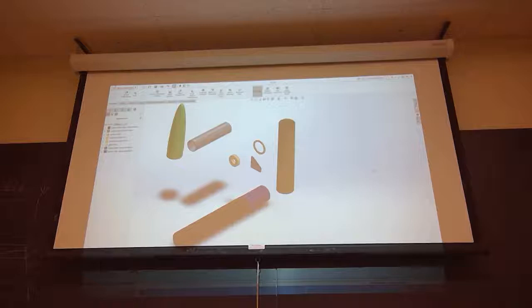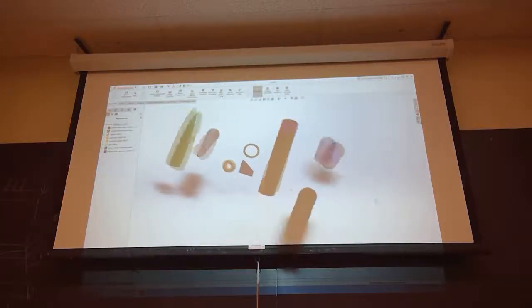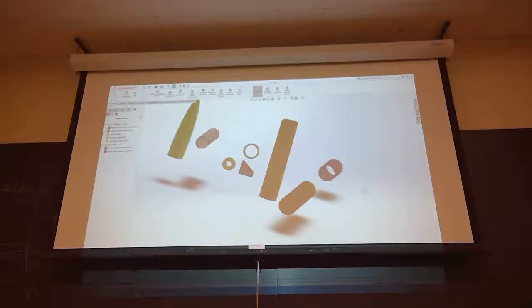So first thing I would recommend you doing is pulling them far apart, okay? To do that, click on the coupler tube and just drag it out. And again, this is why you want one of the parts fixed, so it doesn't move other degrees of freedom. But if it's not, it doesn't matter. All right, so first thing we're gonna do is we're gonna go ahead and mate again.